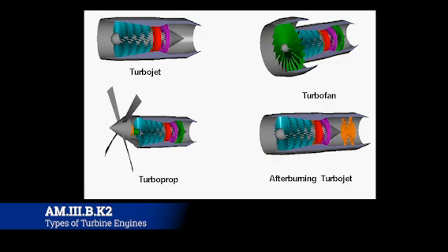You can get by with a much smaller jet engine, so you have a much lower fuel burn, but you still get much greater performance than a piston engine. So it's kind of a best of both worlds approach to turbine engines. However, you're still limited because you have a big prop out the front. You can get so much performance up to a certain point, but then the prop is also a big drag fan that caps the limit of performance.